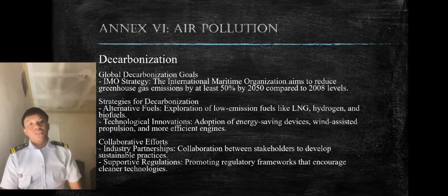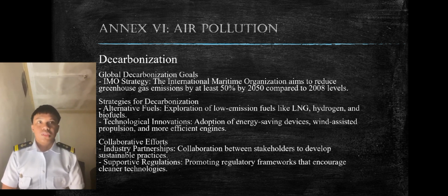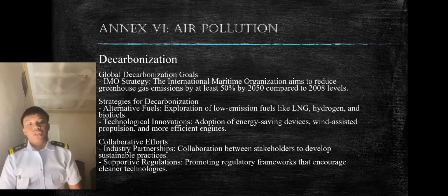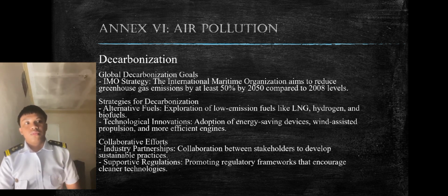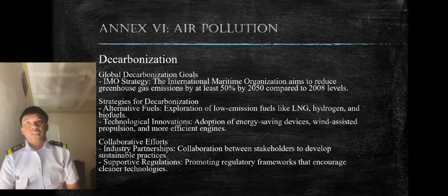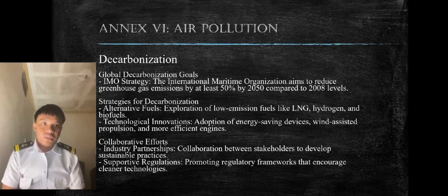The strategies for decarbonization: first, alternative fuels, exploration of low-emission fuels like LNG, hydrogen, and biofuels. The second one is technology innovations, adoption of energy saving devices, wind-assisted propulsion, and more efficient engines.